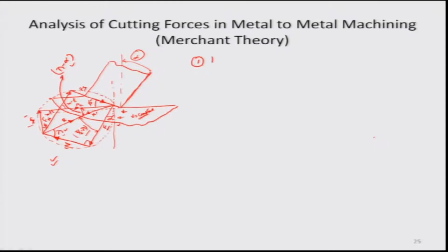The first equation I write here is that Fc equals Fs cos of phi plus Fn sin of phi. Let us see in the diagram how I have formulated that. So, Fs cos of phi is basically this right here, and cos of phi is the component towards the Fc direction, and again the Fn, which is actually this particular force right about here, has the same kind of a 90 minus phi direction when we talk about the normal vector.